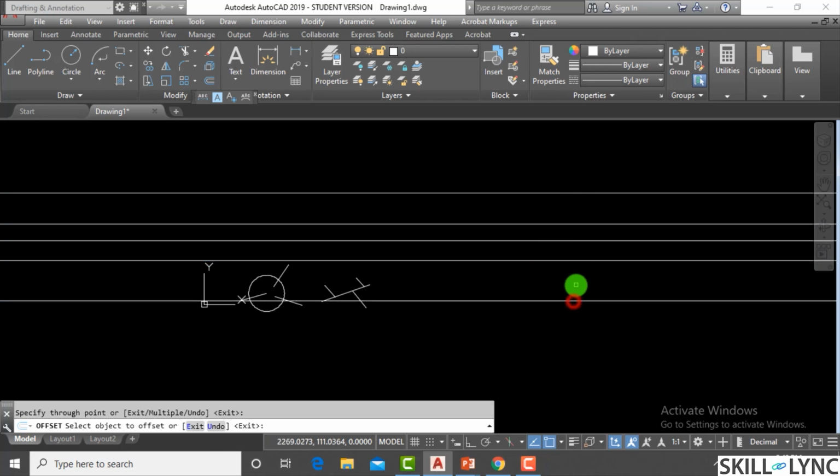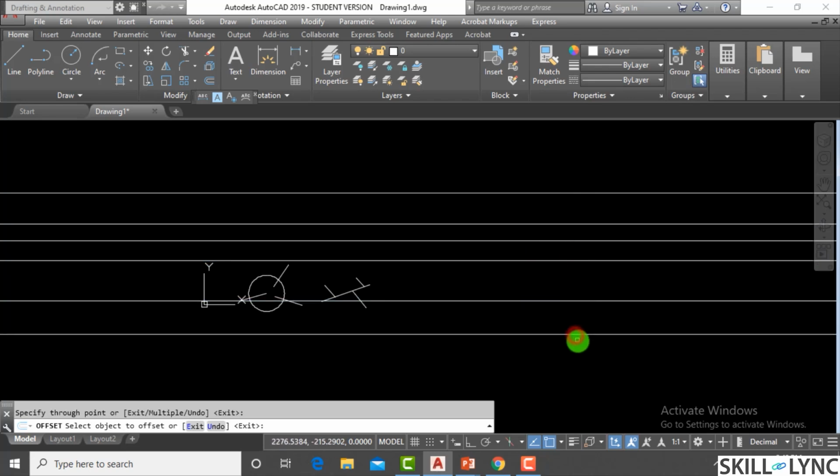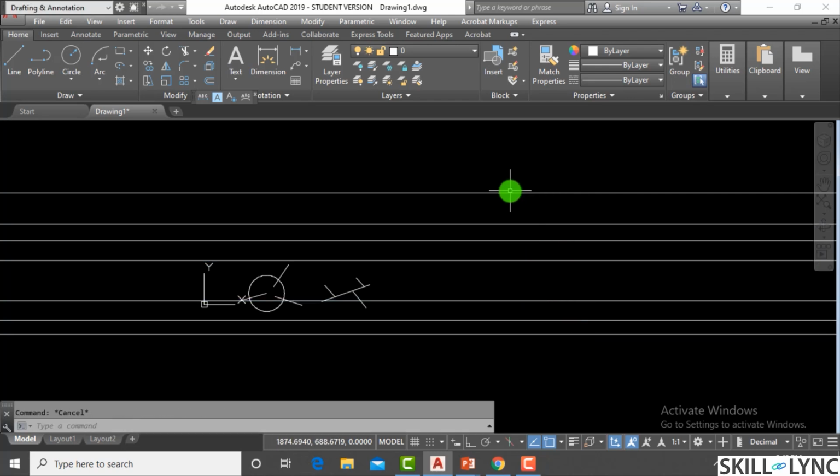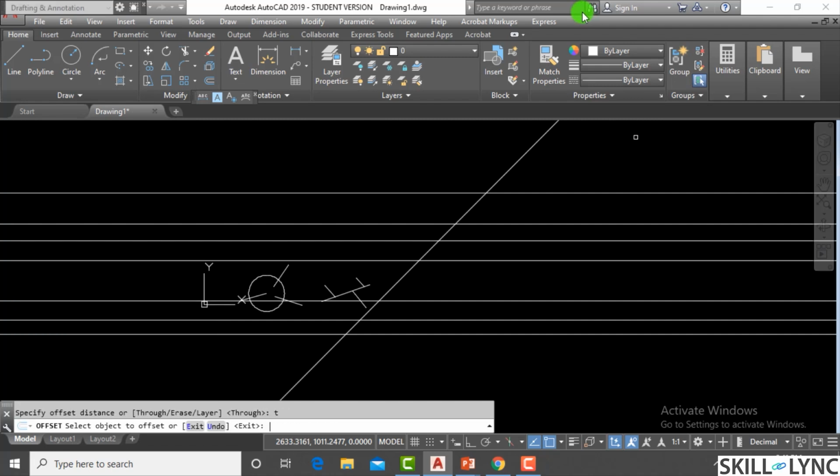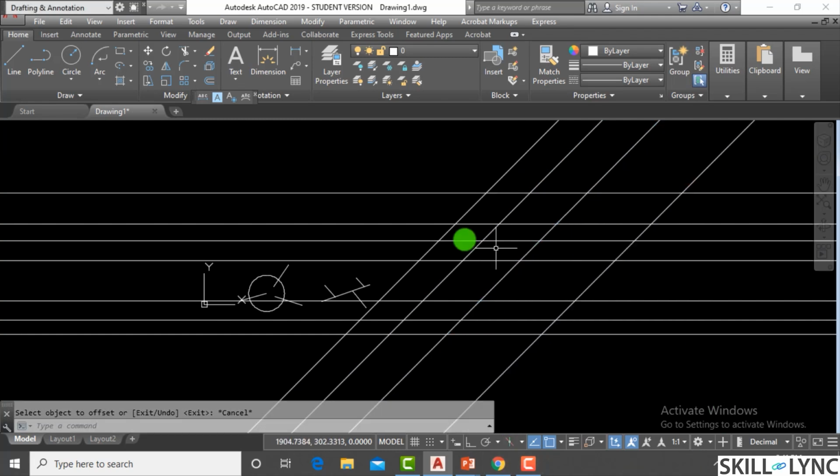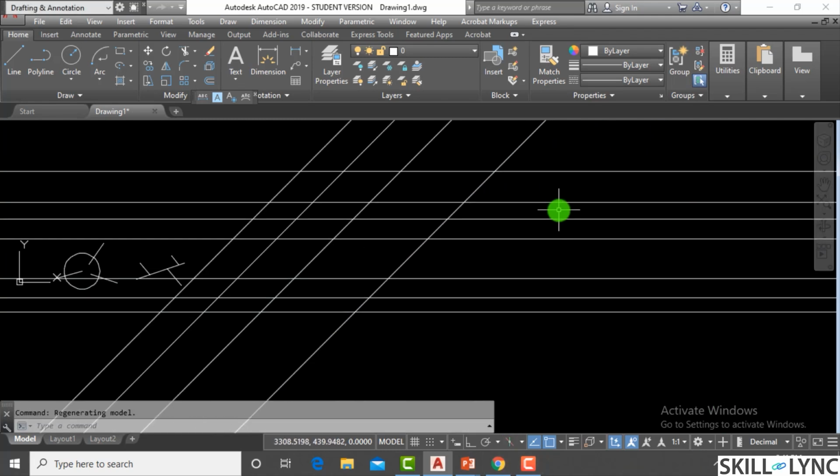Okay, so let me have many X lines, and let me have an X line at an angle of 45 degrees. Let's say offset. I'm taking some examples. Now fence. Fence is this object selection method. Here in the trim they have included cutting edges, this line, let's say the extreme line, and enter.